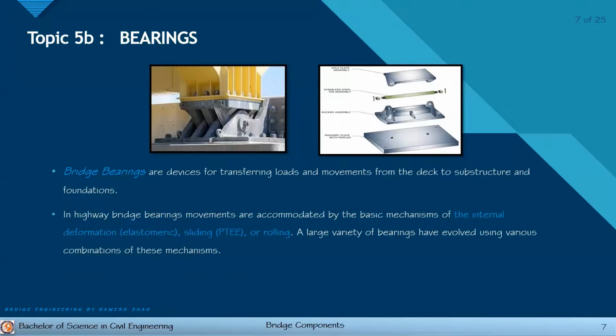Diba, nasabi ko naman kanina kung anong superstructure. These are the decks and beams from the top of our bridges or the surface of our bridges. And these loads, mga loads na makukuha natin doon ay mapupunta sa ating substructure which is our bearing. Sa kanya mapupunta, sa bearing ang mapupunta ang mga loads nating makukuha doon sa ating superstructure. And also, from the bearing, it will go down to our foundation.